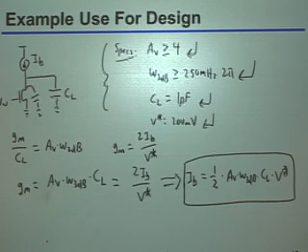So the trick here is that so far everything we've said basically worked to ensure that I got a certain gain bandwidth, but I haven't yet exactly specified what the gain really would be, right? And of course, in order to do that, I need to figure out what the output resistance really will be and how that will vary as I change my design parameters. Okay? Does this make sense to everybody?